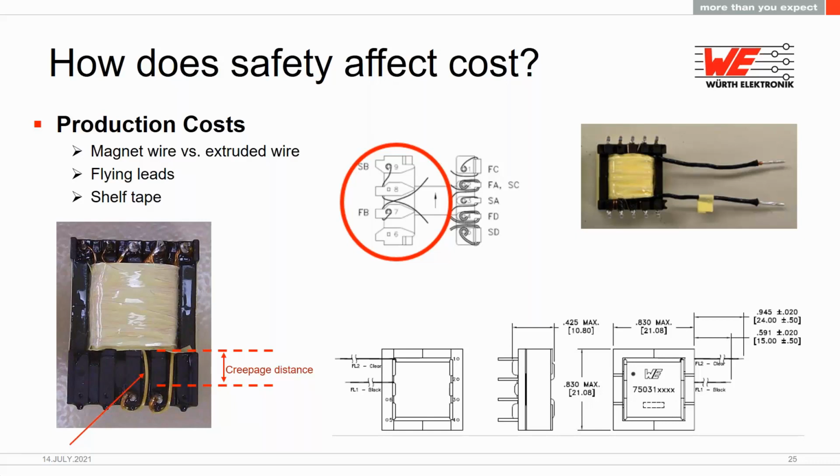Remember, the intention of the extended rail bobbin is for this extension to provide the full creepage and clearance distance from the termination to the windings inside the winding area of the bobbin. Damage that occurs along this insulated wire can violate this creepage and clearance distance if it's not well controlled.